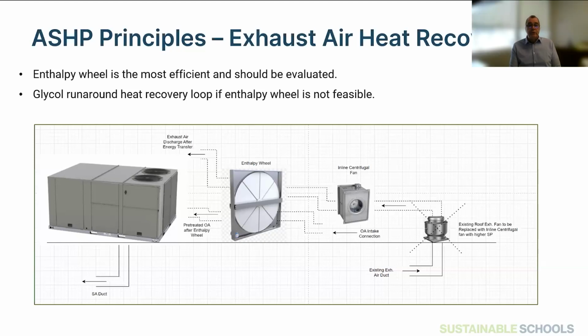So for our new elementary schools with air source heat pumps, they're a hybrid rooftop, so they do have a gas-fired potential as well. So below a temperature that is adjustable through our building automation system or through the rooftop unit itself, we're experimenting with different temperatures currently, but we do lock out the air source heat pump below. Currently it's right around 0 Celsius. A couple of schools we're trying a little bit lower, and then it switches over to gas heat. So there is certainly backup heat for the coldest days.